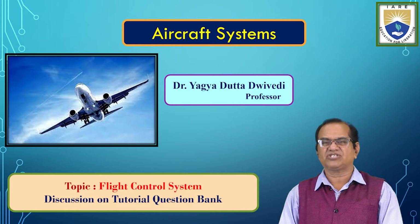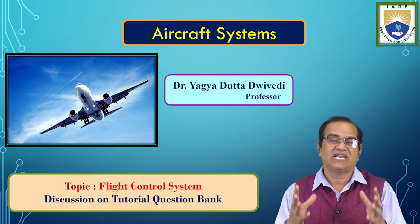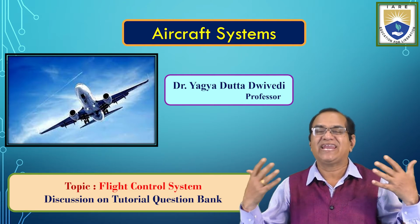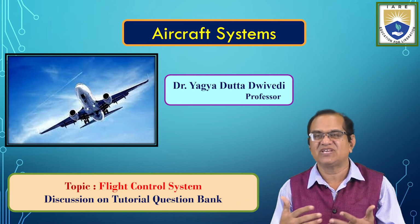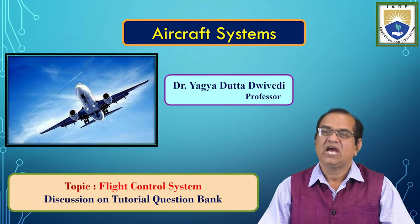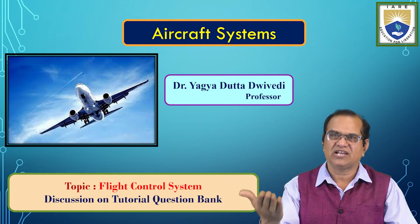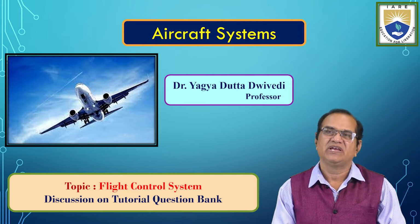The third one is the avionic system. In this avionic system, we can divide into 3 parts: the navigation system, the display system, and the communication system. Navigation means to direct the aircraft from one place to another. We should have some guidance, and this navigation will provide the necessary direction to reach the required place. Communication covers the pilot and the ATC, the pilot and the ground station, and any other communication performed by the aircraft.